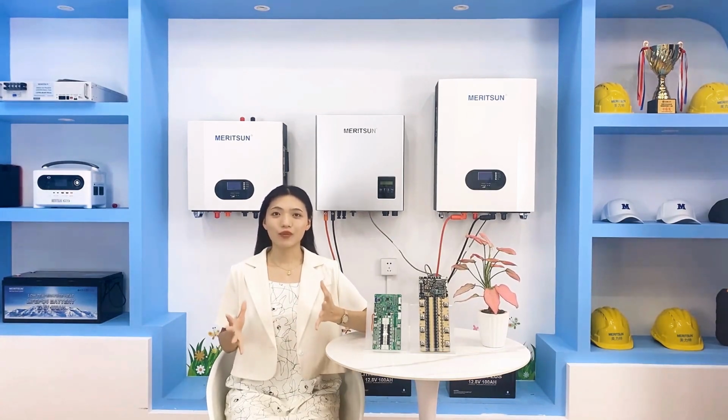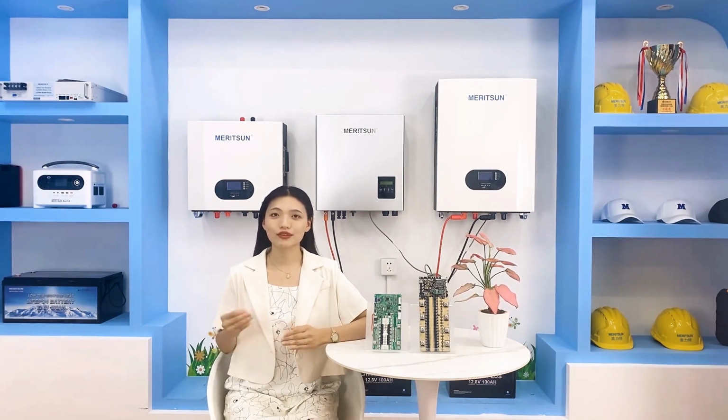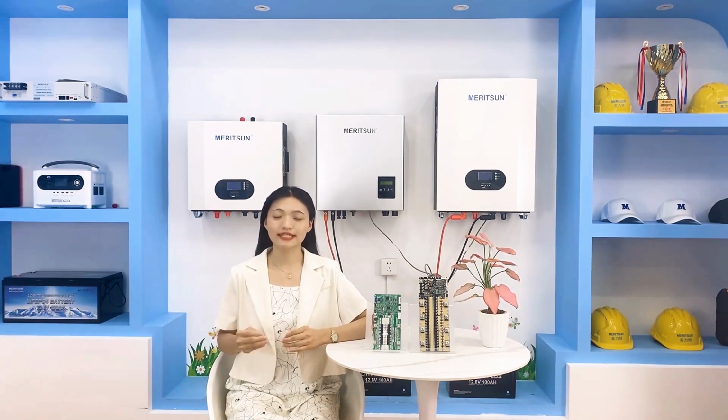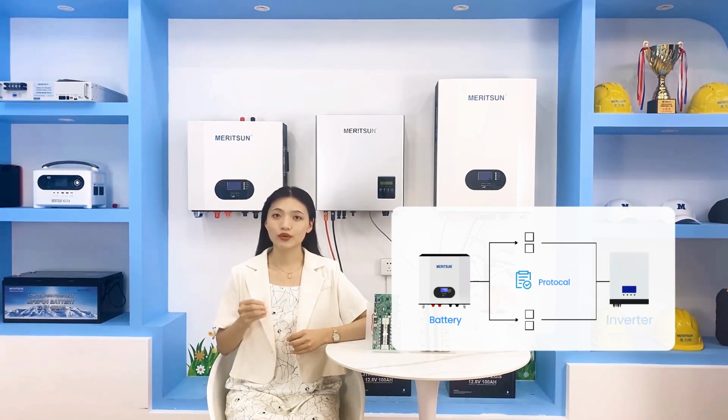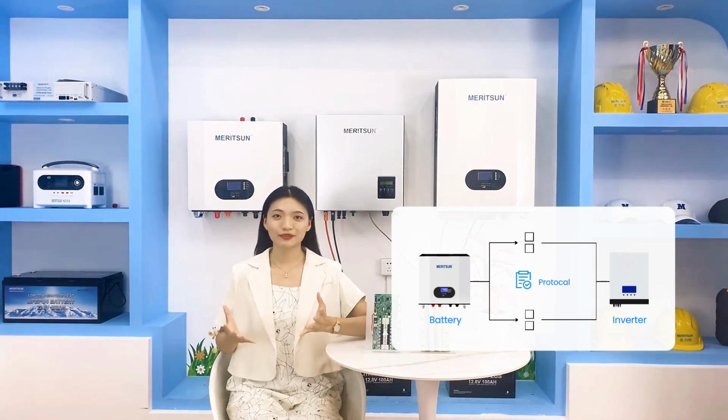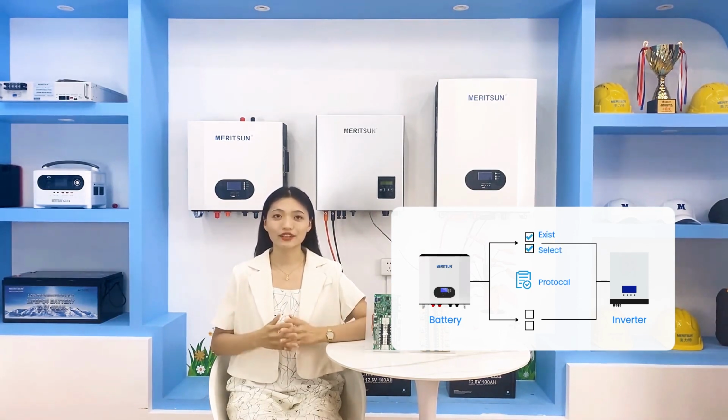In addition to the hardware part, the software part is also very important. As we said before, each factor will affect the recognition of the consistent signal between the battery and the inverter, which will finally affect the communication. The influence of the software section is more critical, because it shows whether the communication channel is open or not. Only when the communication protocol exists on the software and is selected are all our hardware operations effective.